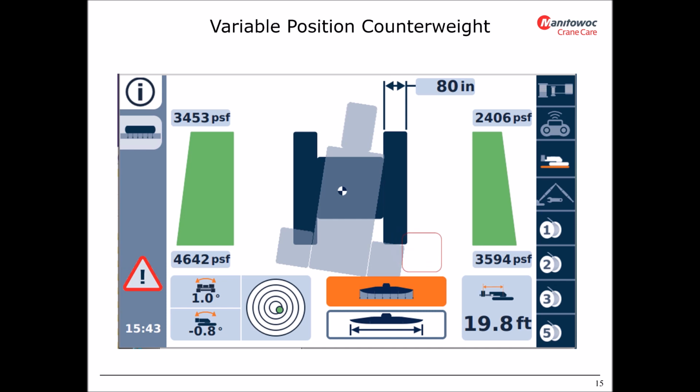Counterweight position for the VPC max or the VPC, depending on how the RCL/RCI display is configured. On the MLC650, see folio F2269 RCL/RCI operations manual for instructions on how to do the RCL/RCI configuration.